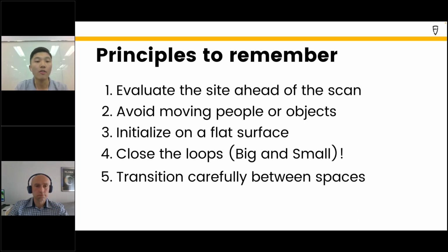Second, you would like to avoid people or moving objects, because LiDAR sensors and SLAM technology, the SLAM algorithm, do not like movement. Keep the area clean and clear of moving objects, people, or vehicles so that you can scan for the best result.